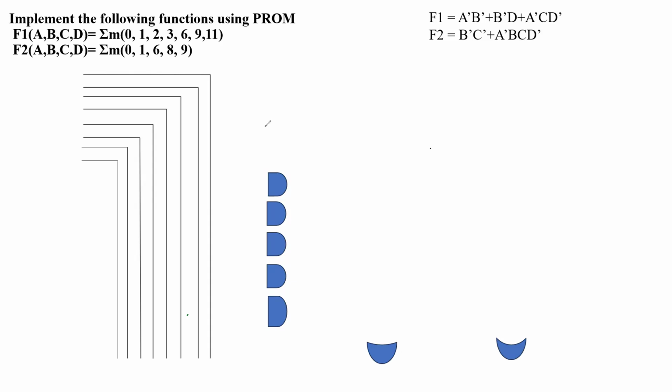So you can understand about this K-map. Here we have 4 variables. So in the K-map, 16 boxes are required. In the 16 boxes, we'll have 4 rows and 4 columns. On the basis of these 4 rows and 4 columns, we can give space for the min terms, where these min terms will be located.